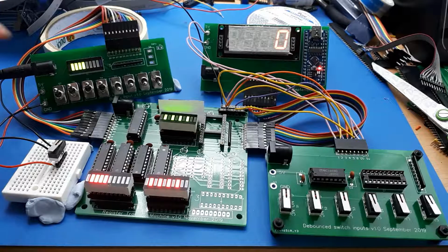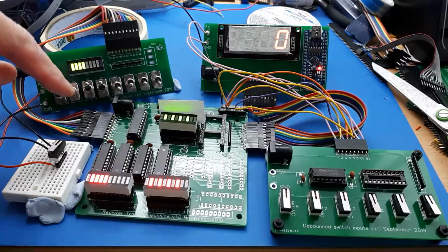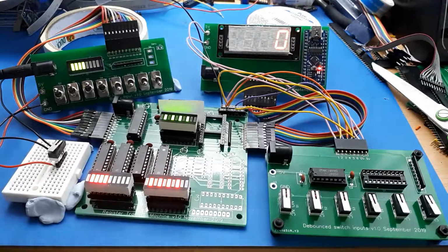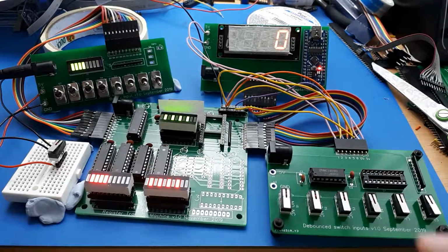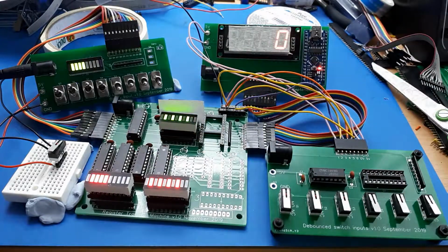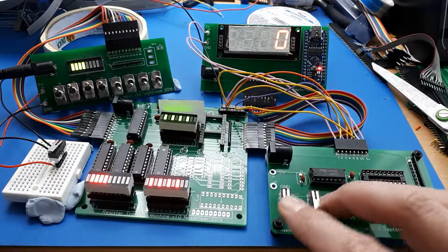So far I've got input devices. This is my keyboard putting data in. I've got an output device, which is reading the data off the bus, displaying my 0. And I have registers which store and publish, but they don't do anything with the data. So there are other types of registers that you can have. One is a register that actually does something with some data. So you could have an increment register: you store a value in it, increase it, and put it back on the bus.